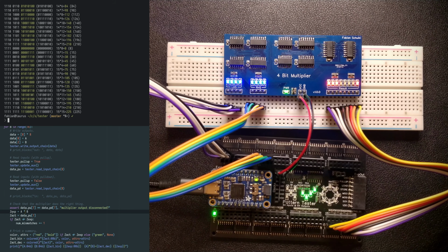And so with this golden model testing, what we're hoping is that we have a description written in software that is a lot simpler to get right than the actual hardware. And we can test this software implementation pretty easily and then verify that the hardware that we've built actually does the exact same thing. And so in the future, when we come up with new PCBs, new hardware designs, we can actually write small Python programs that just run through a few interesting input combinations and check the result, or depending on the complexity of the circuit, we might run through all the input combinations instead.